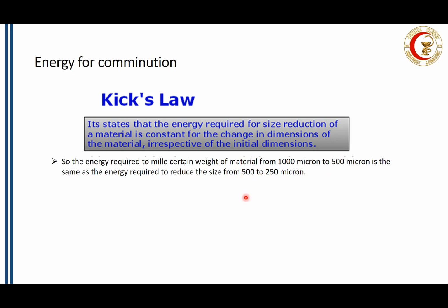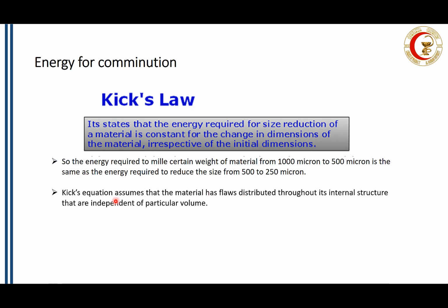Now, Kick's law assumes that the material has flaws, or small cracks, distributed throughout its internal structure, and that this is independent of the particle volume of that material. Now, we know that this is not true because larger particles contain larger cracks or flaws in them, but smaller particles contain fewer, thus we will need more energy.